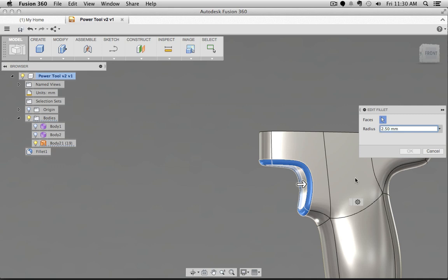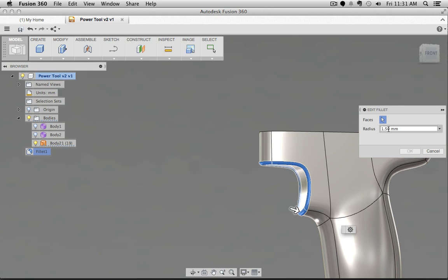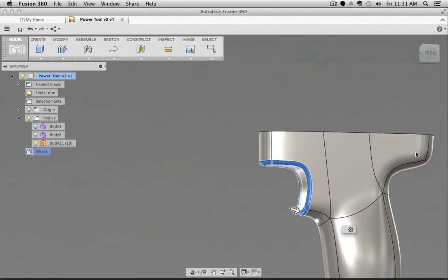And I can even, that's a cool part, so think about those features like the modifier stacks. They provide different input options. So you can see that afterwards, if I double click this one, it opens the dialog box. Edit fillet, right click, maybe 3 millimeter, tab, 1 millimeter, tab. So you can quickly play through some ideas. 2 millimeter tab. Okay.